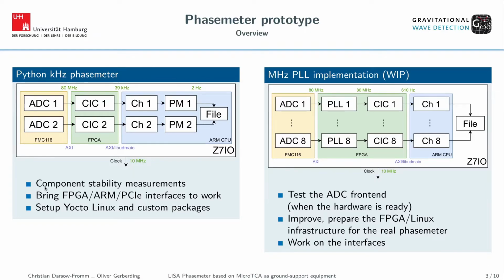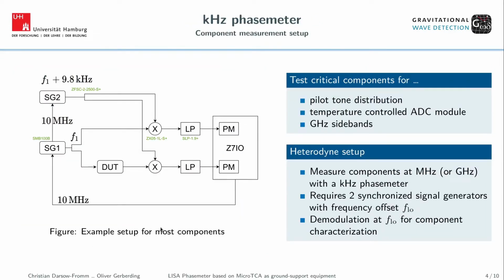And yeah, I said we used that for component phase noise measurements. So that is mainly about components which we use in the ADC or the pilot tone distribution. This is the setup for most of the components. Sometimes it needed to be a bit more complicated depending on the component which we tested.